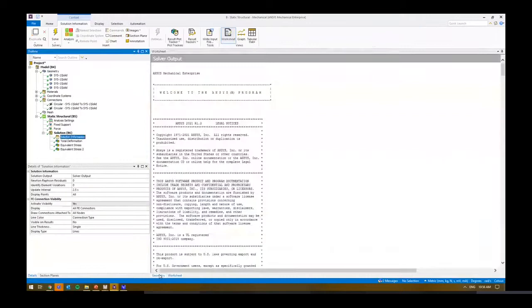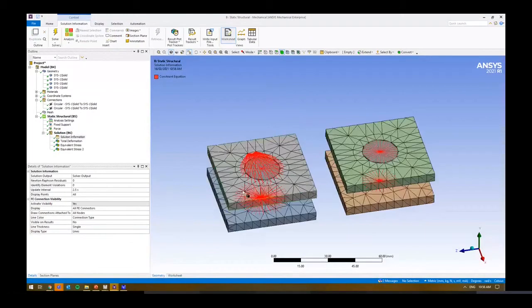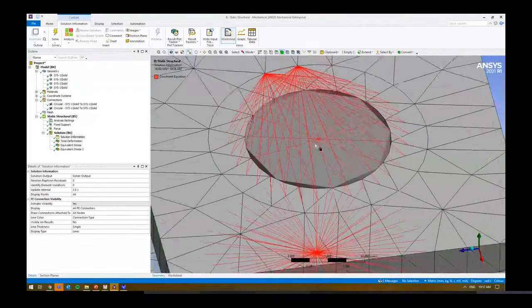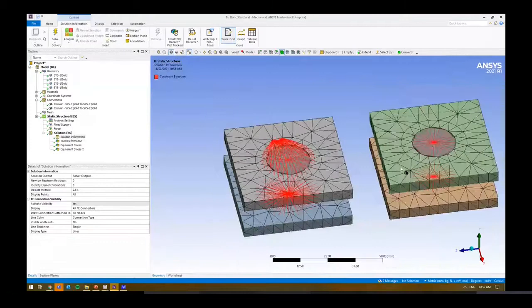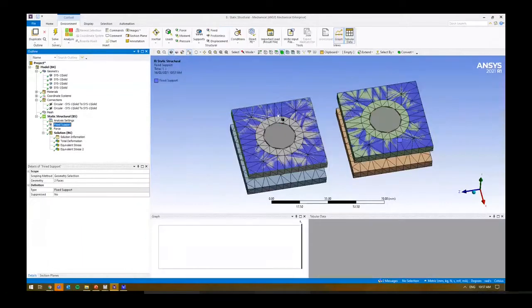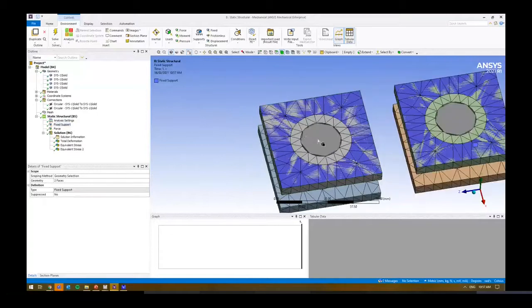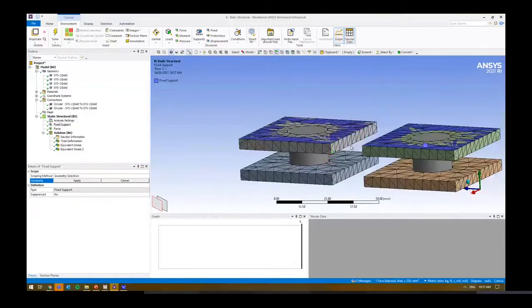If you go to the solution information and select geometry, you'll see, by the way, what the constraint equations are. So you can see there are equations that are being constrained to the tip there, and we've got around there as well. The reason we've got these weird spiders is that we've got some nodes here that are shared between the constraint, the beam, and the boundary condition.